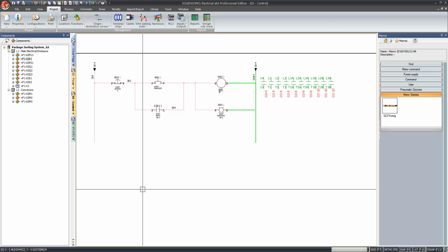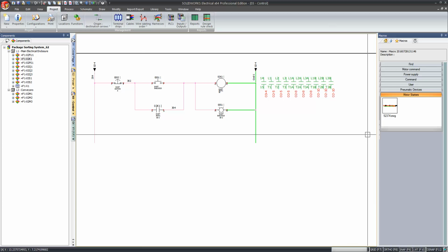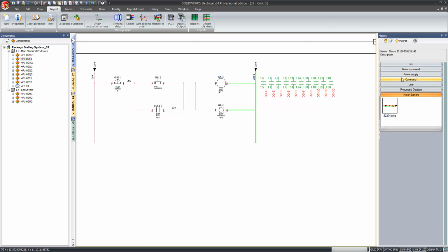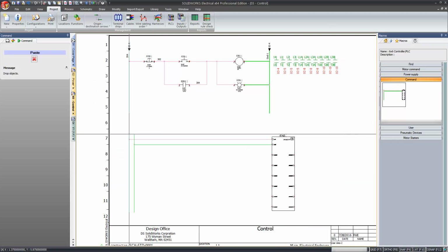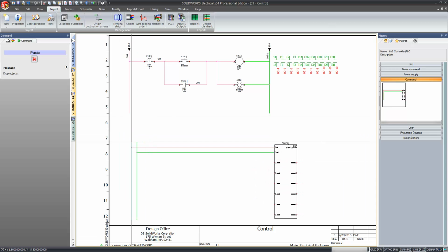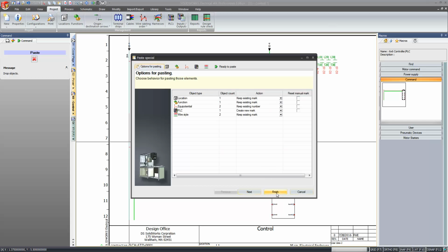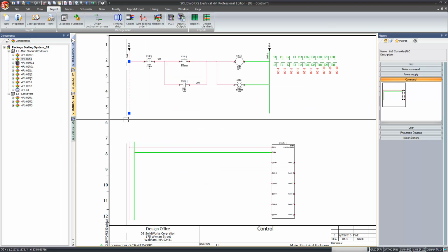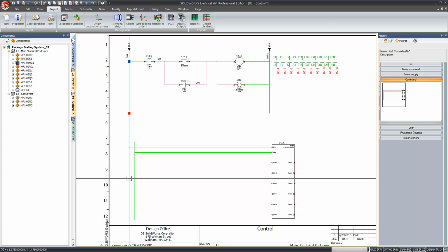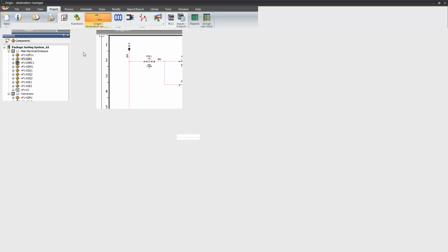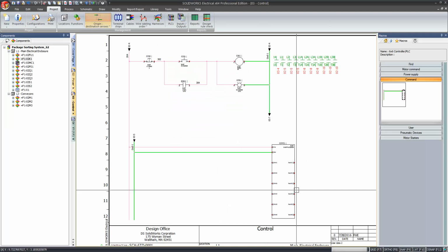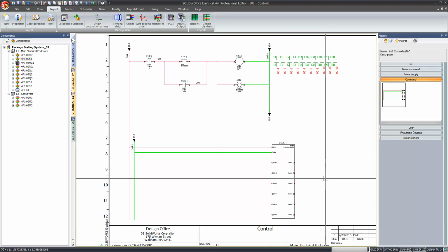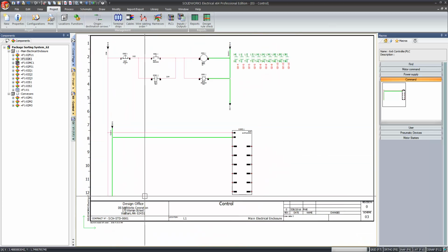Last step here, we're going to create the sensing logic for the pneumatic cylinders that are going to control where the packages go, I guess. And so we'll first jump into the command palette, just drag this over, and we'll place it towards the bottom of the page. I'm just going to line up the crosshair here with that leftmost wire on the screen. I'm going to drag power wire down to connect, and maybe I use origin destination arrows for the ground, just so I don't have to draw a wire across the screen here.